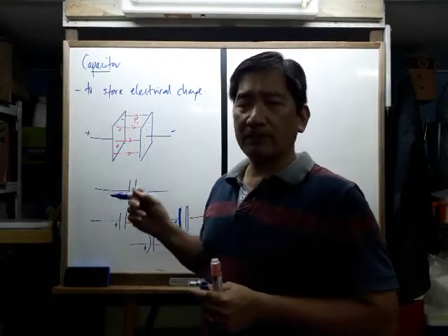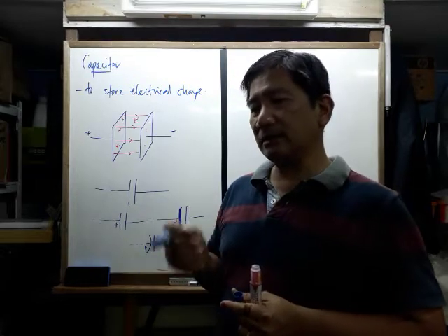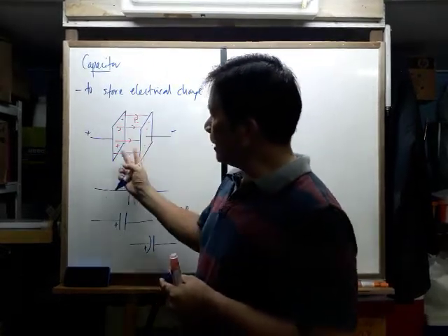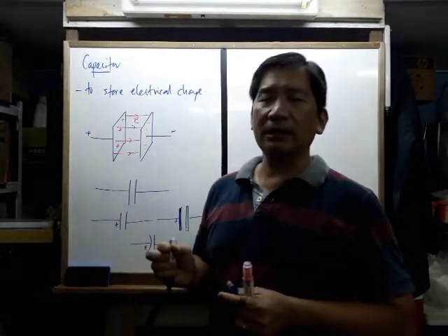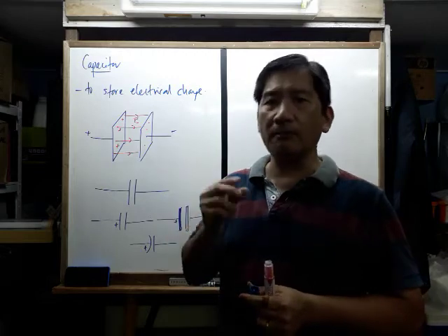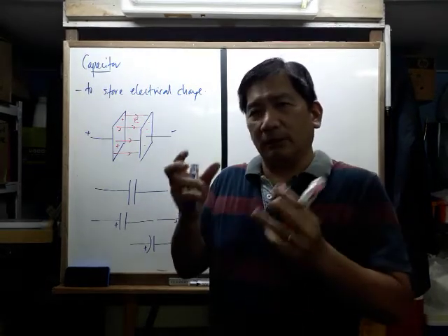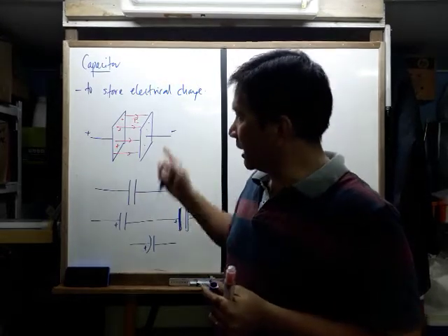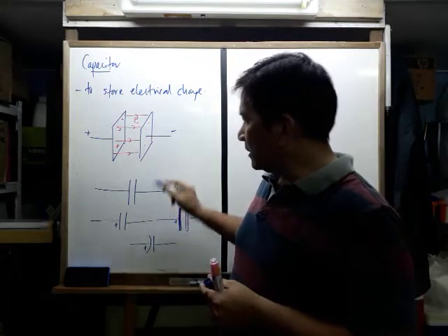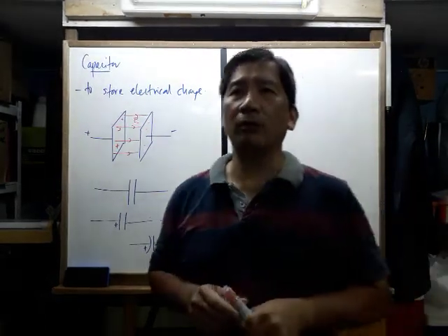Because when you charge a capacitor wrongly, it might get overheated and some chemical inside that insulates the conductor might evaporate, causing pressure and compromising the packaging of the capacitor. It might cause a little bit of an explosion. So that is the capacitor, basically to store charge, and this is its design and symbol.